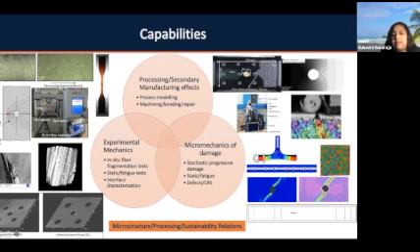In addition to that, we have done detailed investigation of machining, which you could think of as a controlled fracture process. How does the material actually behave when you're trying to remove some material out of it? It could be a drilling process, orthogonal cutting, or milling. These processes have associated friction, so we have measured temperature. We have tried to understand how surface integrity changes during these processes, and how that can be correlated with the structural integrity of a component.